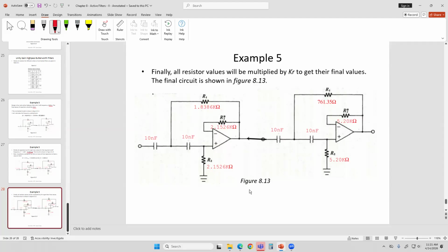The first step of the procedure is, first you calculate the frequency scaling factor based upon the required value of the cutoff frequency. Actually, let's move back. The first thing is to find the order of the filter. That's important. Based upon the cutoff frequency and the stop band frequency that is given to you, based on their ratio, calculate the value of x, which is the x-axis of that curve, and then find the smallest value of n that will satisfy your order. Now choose that, whether it is 3, 4, 5, 6, or 7.